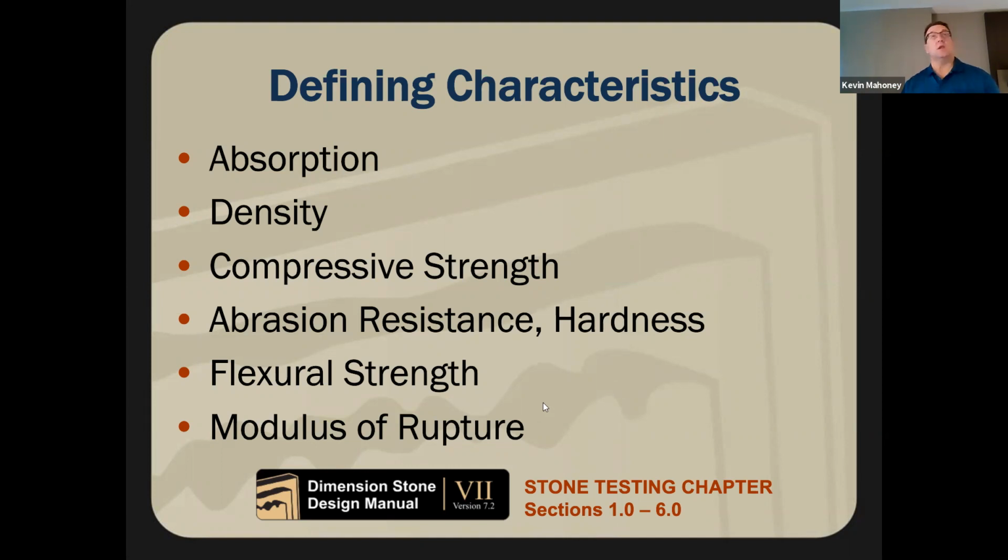Flexural strength, really when we're talking about stones, L over 360 is a term that we use in the tile industry to talk about 360 inches, allowing for 1 inch of movement up and down without any cracking or degradation to the product. Sometimes with stone, those flexural strengths are L over 480, 480 inches, 1 inch of movement in and out, and L over 720 on some stones are just as important on the walls, because stones, depending on how thick we cut them or how we hang them, become more fragile. So flexural strength is an important term.